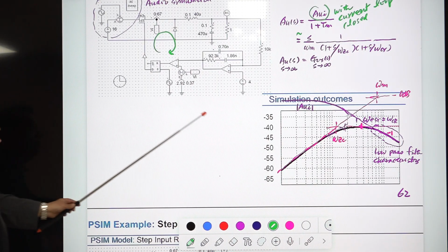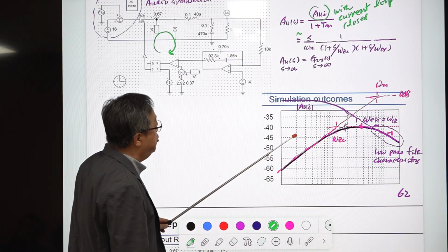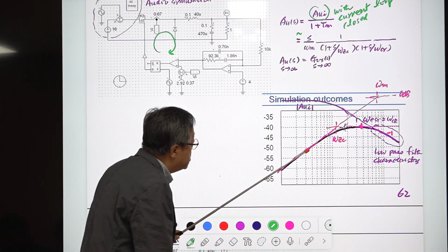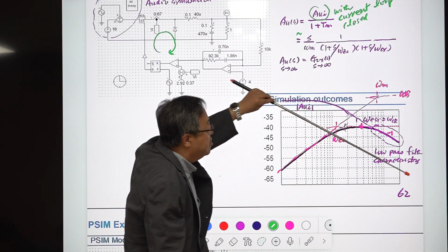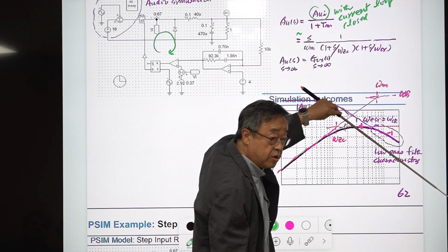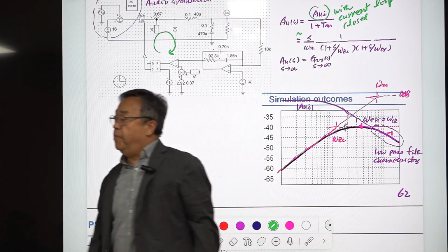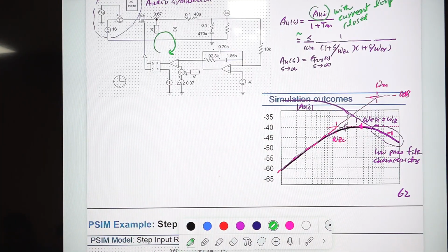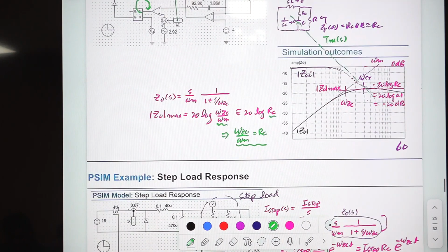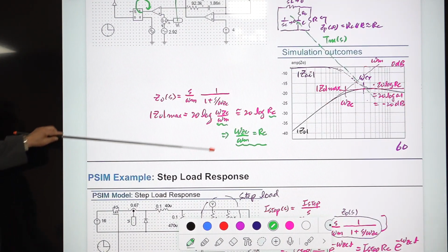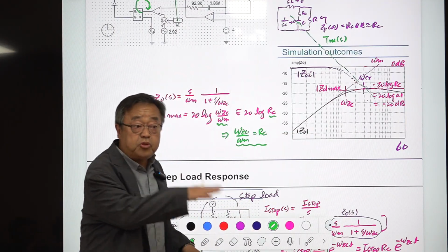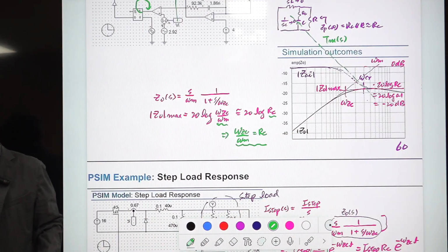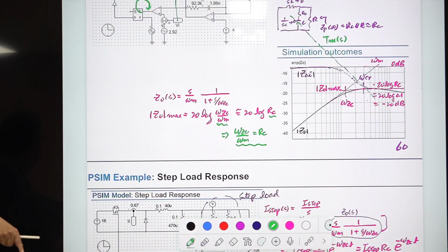So this is the closed loop input to output transfer function, with a low frequency line segment, some mid-band gain and the high frequency asymptote. The big difference compared to output impedance is that output impedance has a finite value, but this input to output transfer function, audio susceptibility, has a -1 declining slope at high frequency.